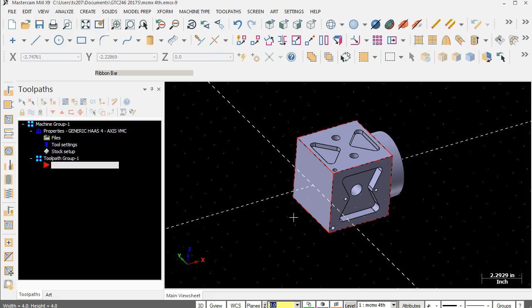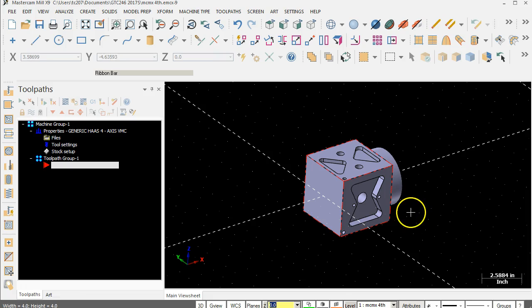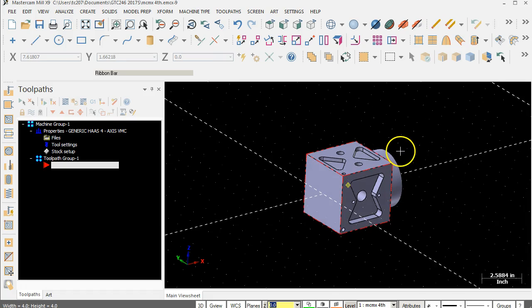All right, so this is a small enough part. One thing that I might consider drawing in is, if this is a 120 millimeter, if this is a 200 millimeter platter, I may go ahead and do a sketch out here on the end that represents that platter so I can have a visual reference for clearance. The closer we are into the chuck, into the platter, the more we have to be concerned with these movements, and especially the larger you get up to a 300, whatever it is, 300 or 310, then clearance is definitely going to be an issue.